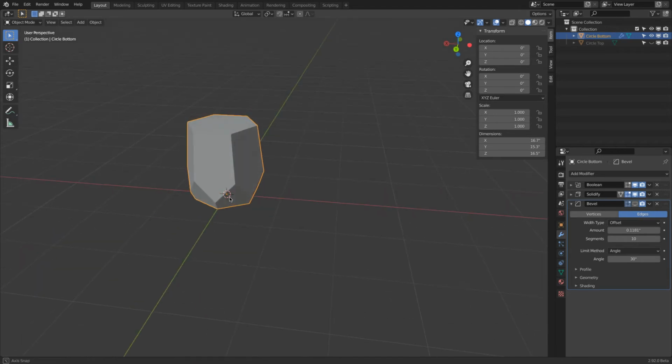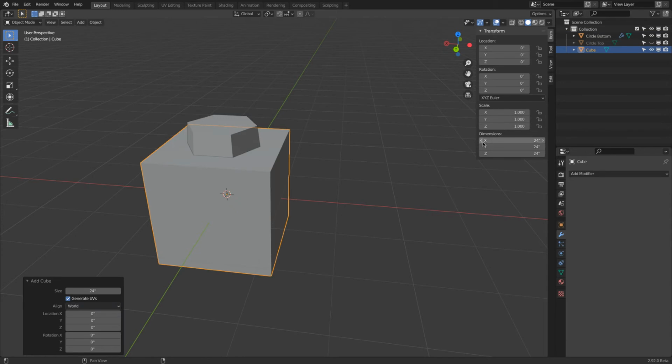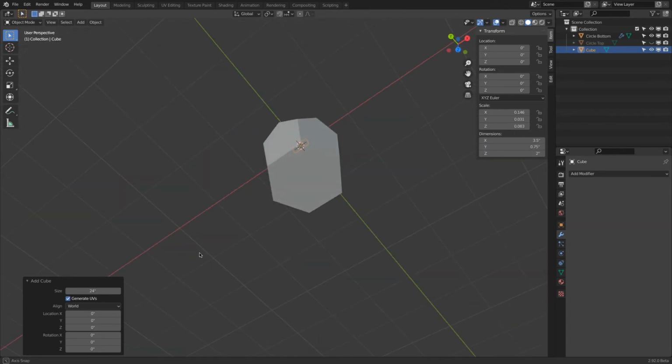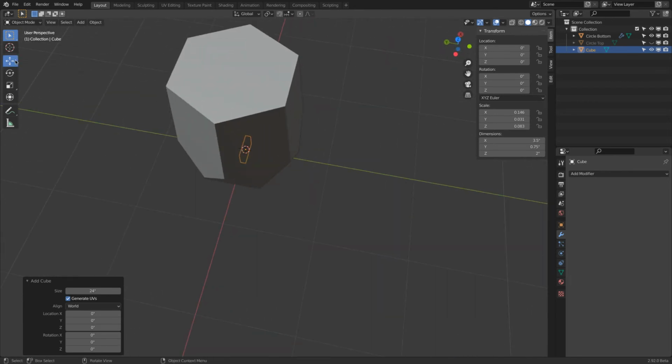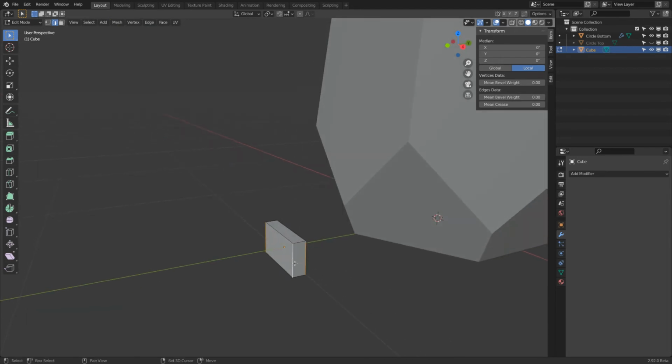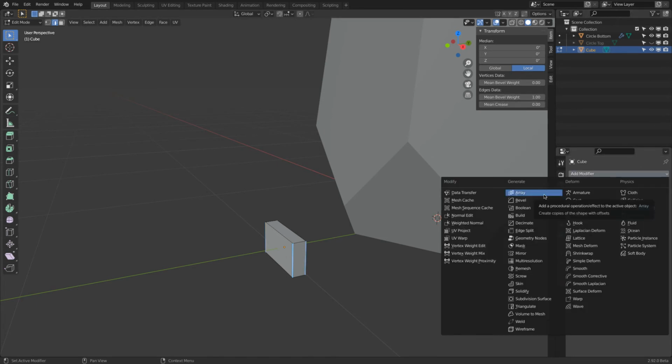Because what I would like to do now is create the opening for the hand. Add cube. Along the X, we make this 3.5 inches. Along the Y, 0.75. Along the Z, 2 inches. And along Y, I move this one out. Go to edit mode, edge select. Select the 4 edges. Give everything a weight, or type in enter and 1.